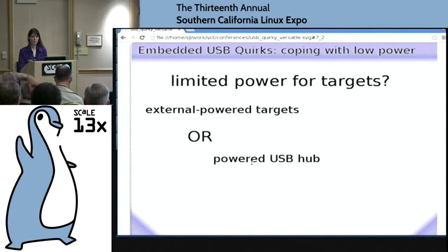But if the board is mostly 3 volt, it might have a special boost just to provide the USB 5 volts. But if it's just passed through, in theory you could just put a bigger power supply on it, except the regulators don't always accept it.